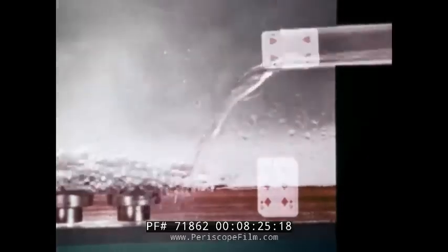At the top of the column, it's coolest, and only the lightest fraction is left, the 4s. This vapor is condensed, but it still contains stray 6s. So here too, a steady stream is returned to the tray below. The 6s remain in the tray, and the lighter 4s are re-vaporized.